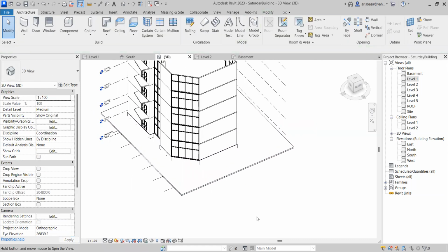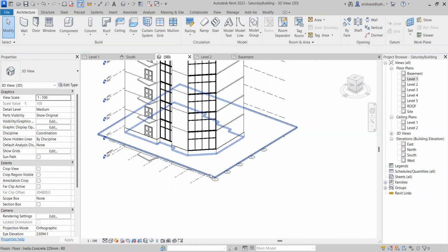First create the floor. Create the floor, the big rectangle, and then trace the outer line of your building. Just follow the line. So you draw first the big rectangle, and then draw the line of your building, so this will be cut automatically. Use your line tool.